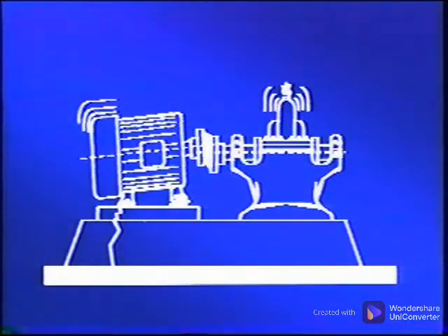Thermal growth is the change in the physical size of the machine from the offline condition to the online condition. If thermal growth is not taken into consideration during the alignment process, the smooth running condition at restart may become a rough, vibrating machine when it returns to its normal operating temperatures.